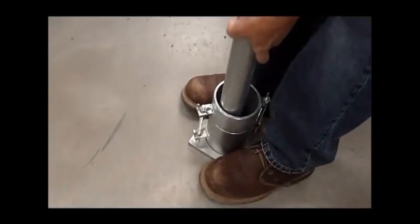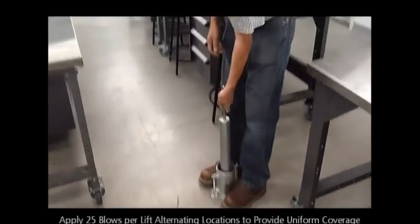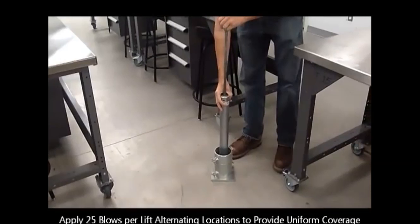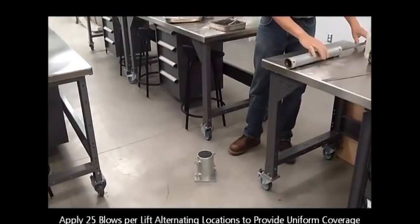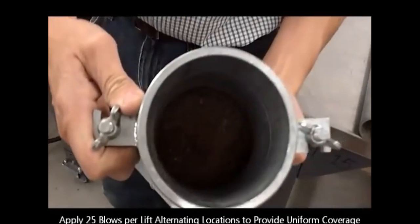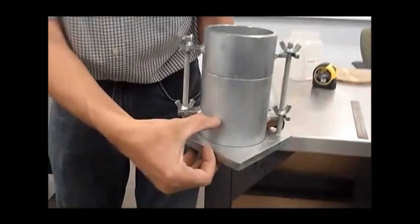So I'll give 25 blows uniformly across the soil surface, and after compacting, the layer should approximately fill 1/3 of the mold. We are compacting in 3 layers, so it has approximately filled 1/3 of the mold.